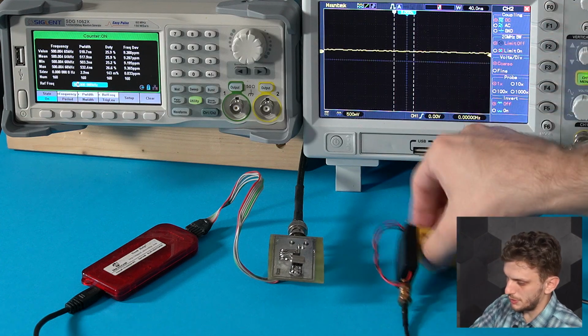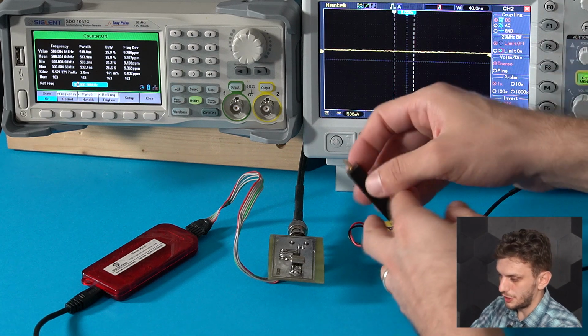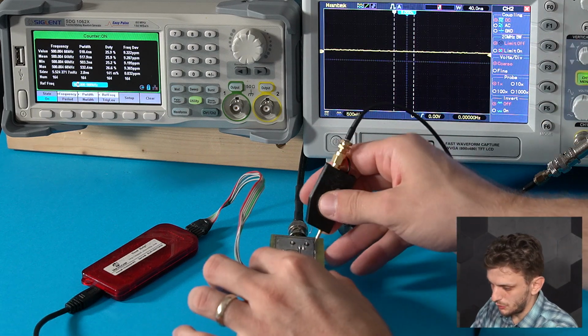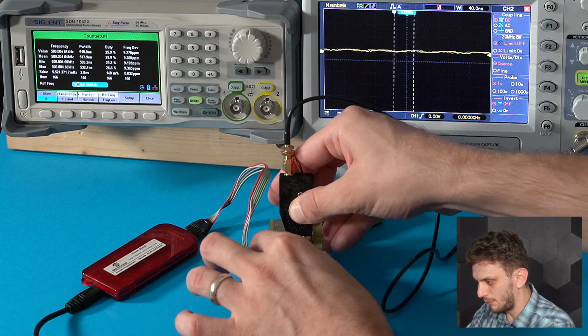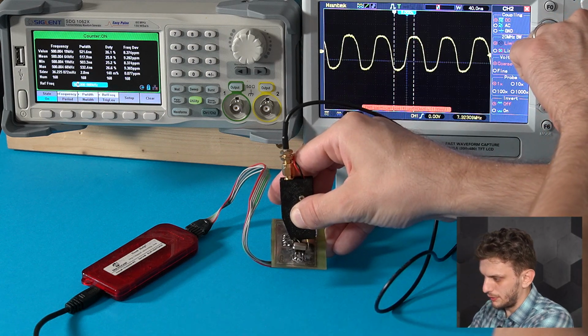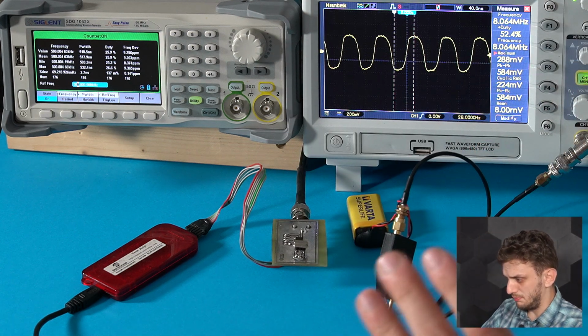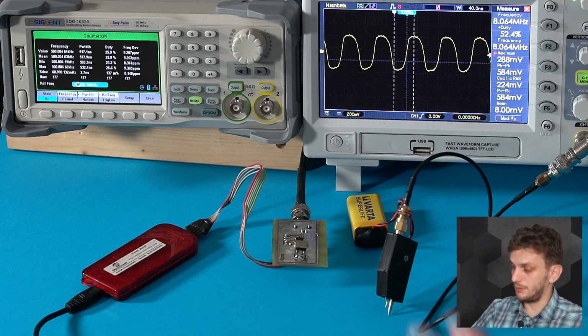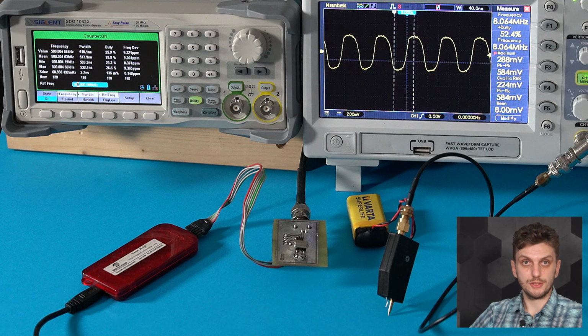So now the probe is powered, connected to the first channel of the oscilloscope with a 50 ohm termination, and if we connect it into the circuit, so onto the XO pin of the oscillator, we can see a signal appearing. So it's running at 8 MHz, and it doesn't look perfectly like a sine wave, but this is the sort of signal we can expect when looking into the oscillator.